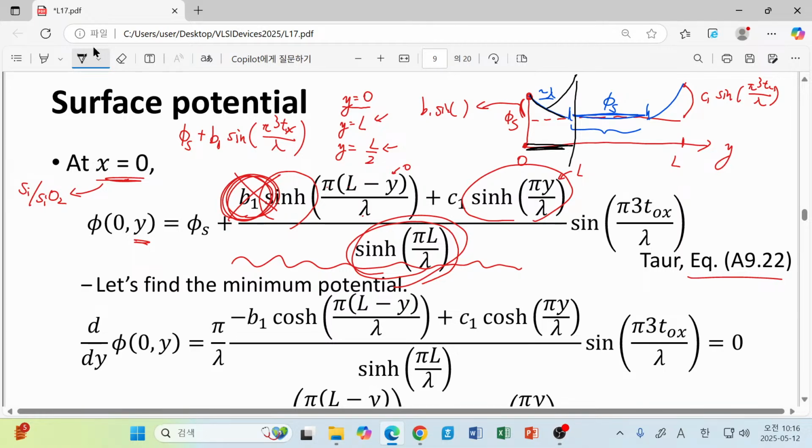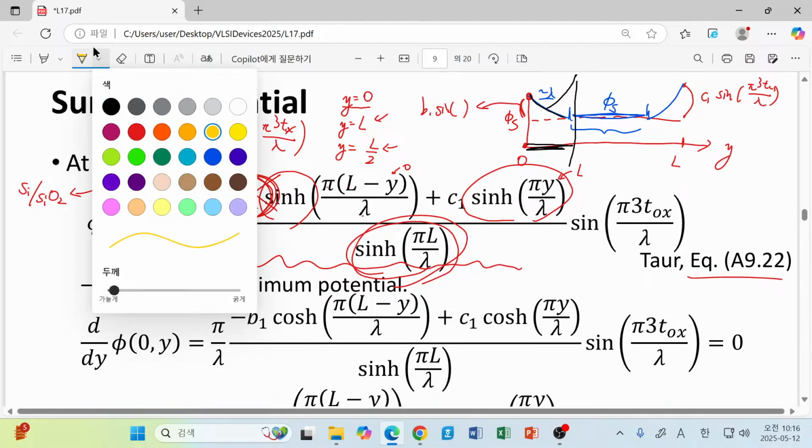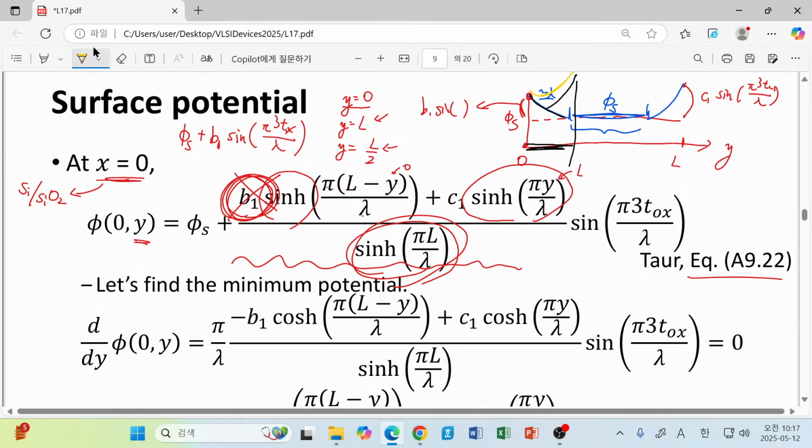By summing them all, eventually we will have the function that just looks like this, and that is much higher than the long channel counterpart. So that is actually the increase of minimum potential, and that is also interpreted as reduction of our threshold voltage. Even without paying the additional gate voltage, now we can see the reduction of a potential barrier that is interpreted as threshold voltage roll-off.